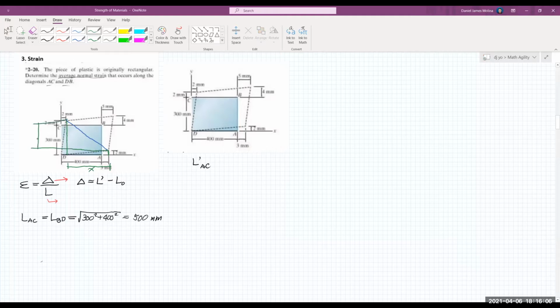Somewhere there. This is the deformed joint A, and this is the deformed joint B, so that it will be easier to see. Okay, so for us to solve for the deformed length of AC, by Pythagorean theorem, it's the square root of x squared plus y squared, given from this figure. Let's say figure 1.